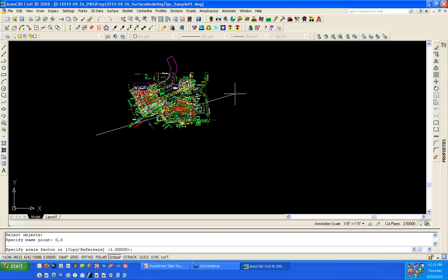And now it prompts for the scale factor. Now this is something a lot of people don't know. Even those of you that have been using it, I come across a lot of people that aren't aware of this next little thing. Rather than use my handy-dandy calculator and do 1/12 to get a 0.083333, AutoCAD does allow you to just type in 1/12. And the good thing about that is there's no rounding involved, so it's going to be as exact as it can be.